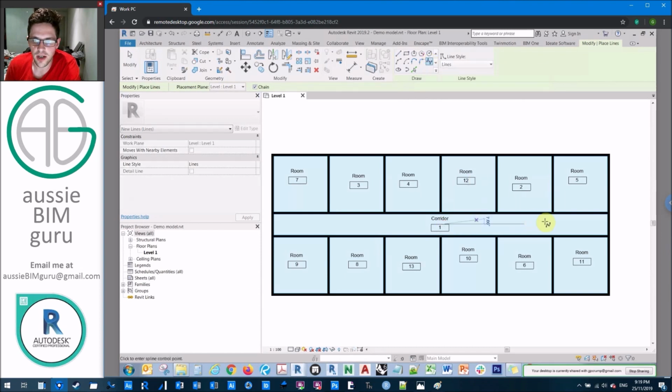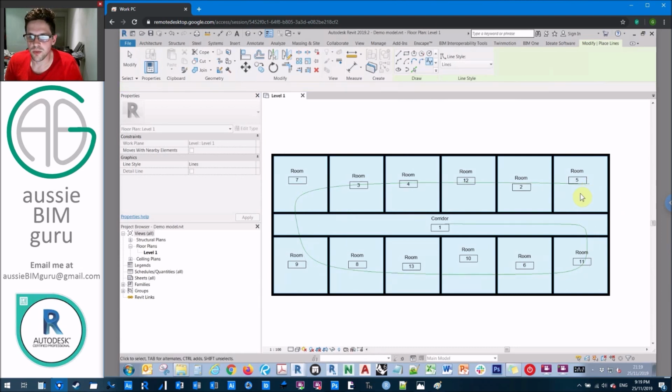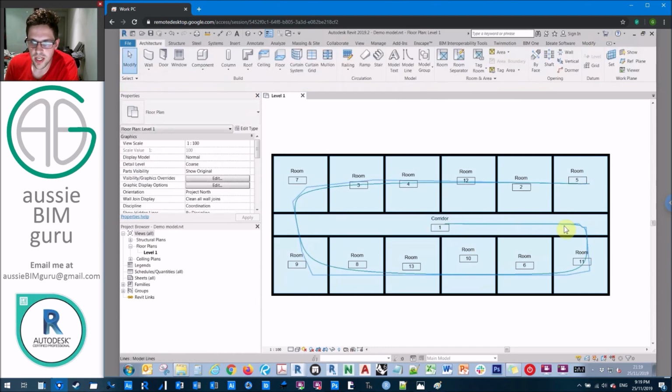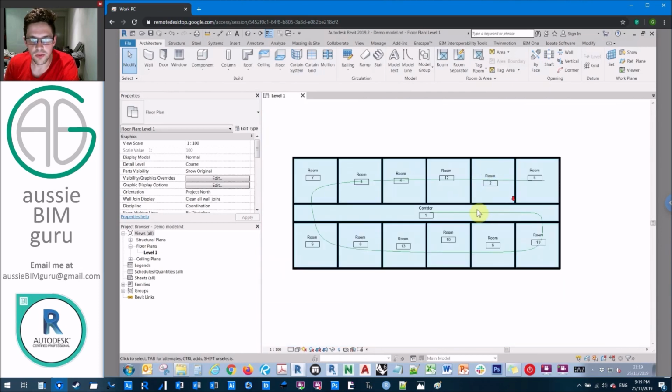So we'll just start, and if you ever need to go around a really tight corner with a spline, just create a lot of control points, click a few times, and then you can just go through, and we're going to cross the corridor. And it's okay to go through the corridor again because we're already going to have intersected the corridor at that point. Because remember that a room's boundary is on all sides, so we're going to actually intersect the corridor here at its edge before we go into room 11, which we're going to be making room 2. Anyway, this will be our input.